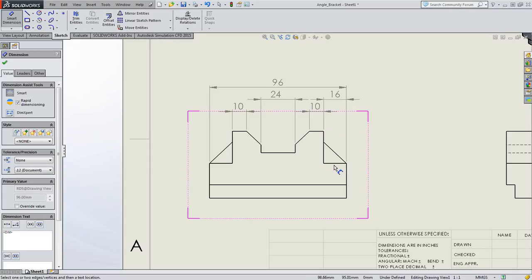And this is the tricky part. We have these nice dimensions, and now we have to squeeze an angle in. So let's try going from here to here. 2 lines. Drop the 45. Now this, you do not want dimensions to cross over the part if you can help it. So we could bring this in. We could do something like this. No dimensions are kind of overlapping. I mean, we have this, but that's something we can't avoid. It's not over the part. I can see that it's this line to that line, and it is 45 degrees.